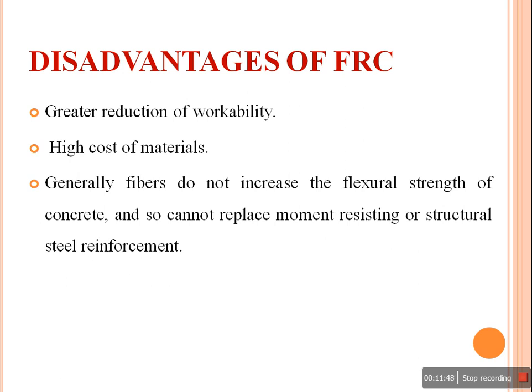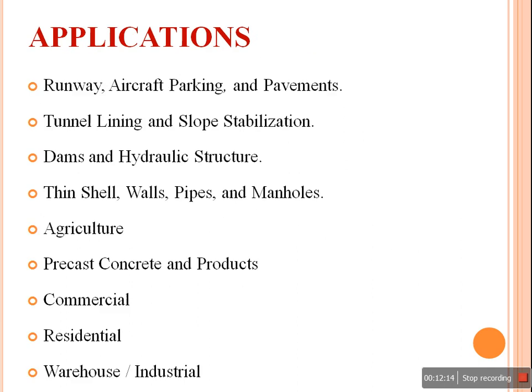If we go with glass fibers or steel fibers, these are rather costly materials. Generally, fibers do not increase the flexural strength of concrete and so cannot replace the moment resisting or structural steel reinforcement. They cannot replace the structural steel, they just improve the tensile strength of concrete.